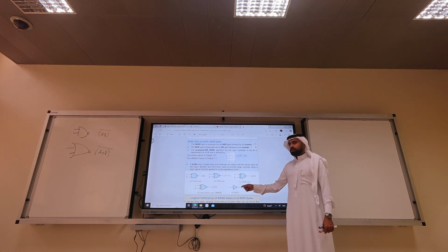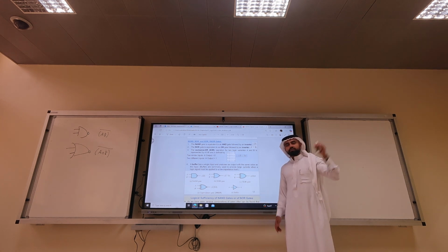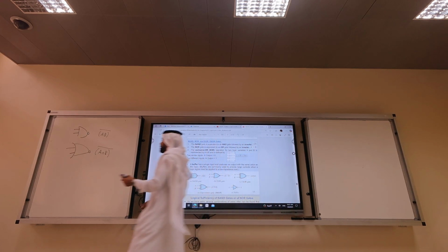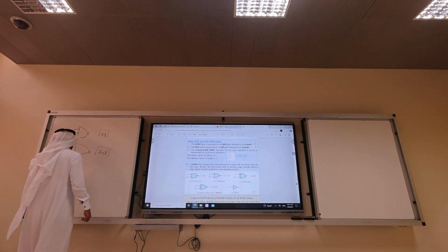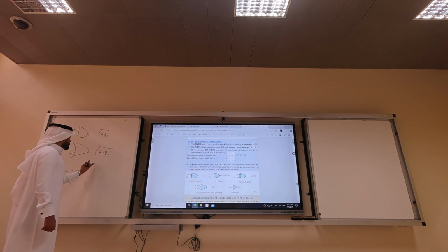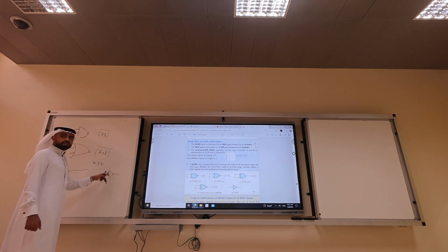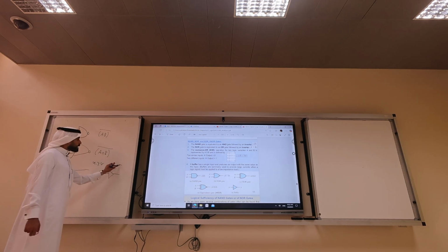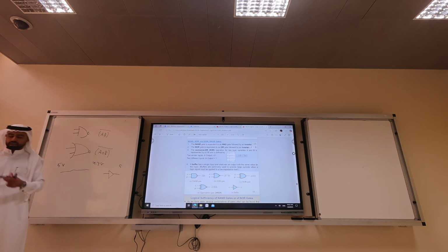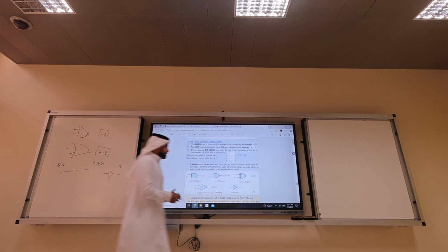That's the benefit of the buffer. If your signal is, for example, in digital, you have 5 volts, and for some reason it became 4.3 volts. If you put a buffer, remember the buffer is powered by the circuit, by the chip, like an op-amp, you will get back the 5 volts. That's a clear application to boost the strength of your signal.